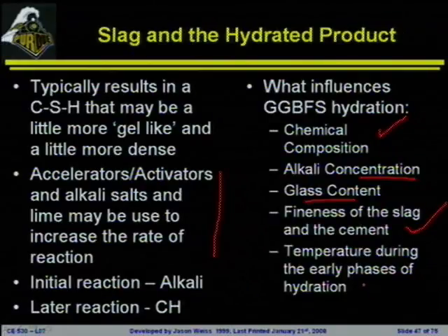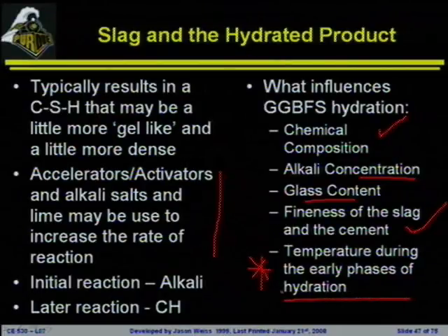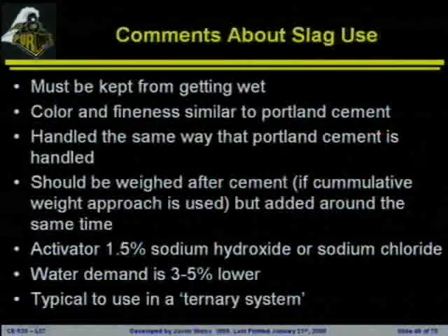And then one of the other key issues, and we'll keep coming back to this, and talk more when we discuss early age concretes and curing, especially with supplementary materials: they can be very sensitive to changes in temperature. They're typically more sensitive than ordinary Portland cement to a change in temperature. A lot of times you'll hear people say, oh, we tried to do this on a cold day, or we tried to construct on a hot day and we got very different results. It's like anything else. You need to get used to it. Once you get used to it, you can understand what steps need to be taken to get a normal hydration rate and a normal strength development process going with these materials.